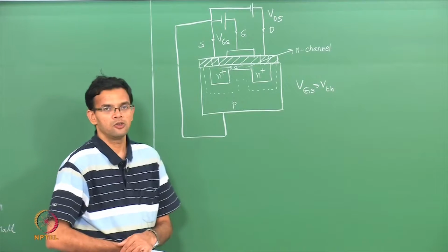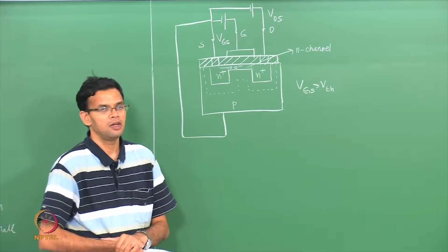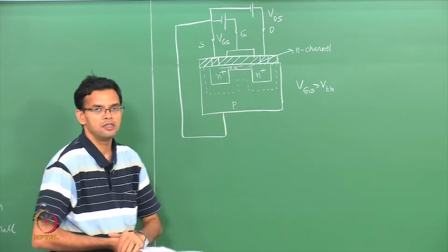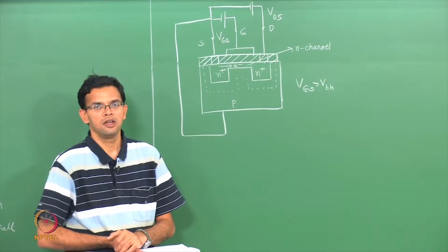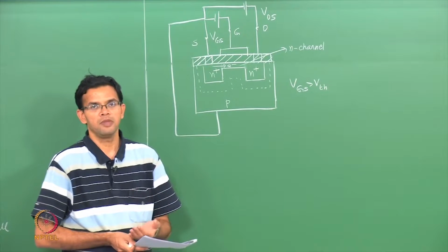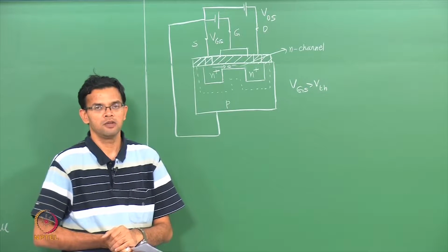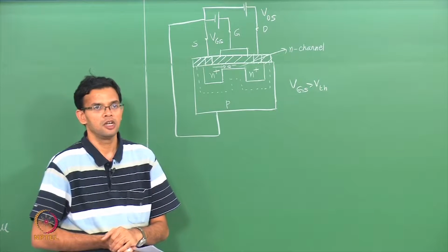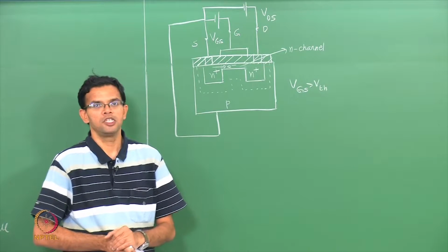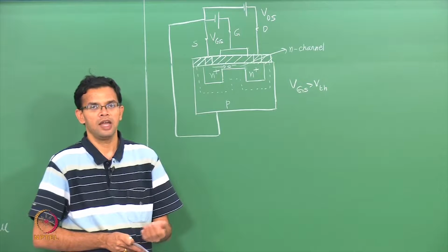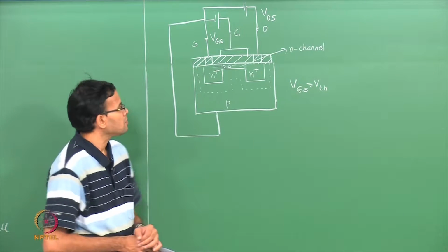Thus, the gate source voltage essentially acts as a controlling parameter in order to control the current in the MOSFET, and this essentially is the transistor action, where the voltage between two terminals determines the current or the voltage between other two terminals. You can also say that this gate source voltage acts as a switch, so it helps to turn off or turn on your transistor.